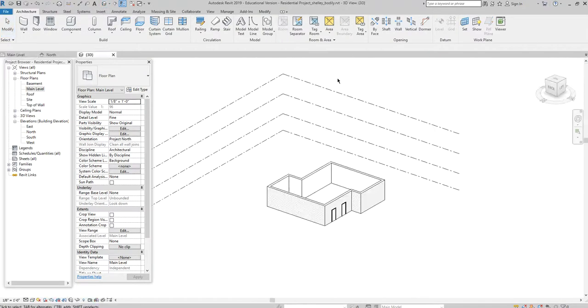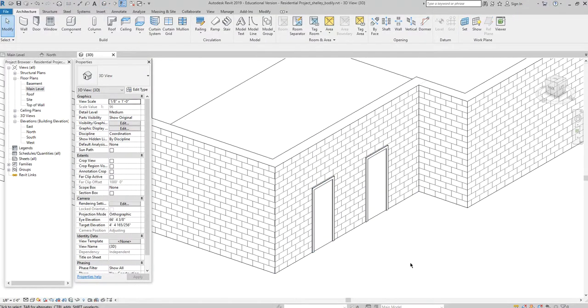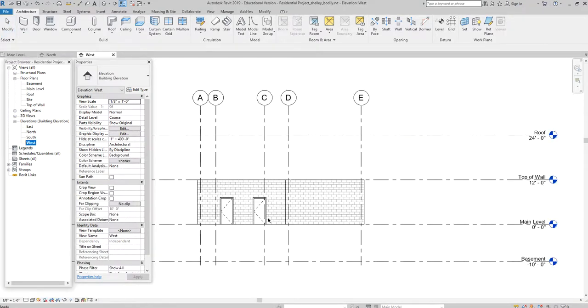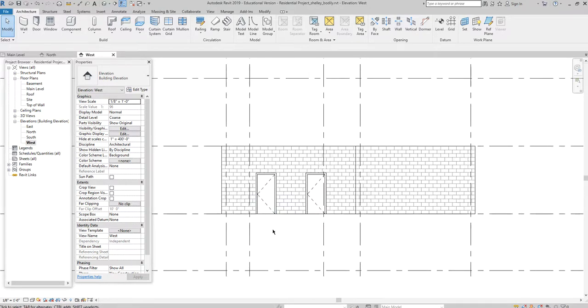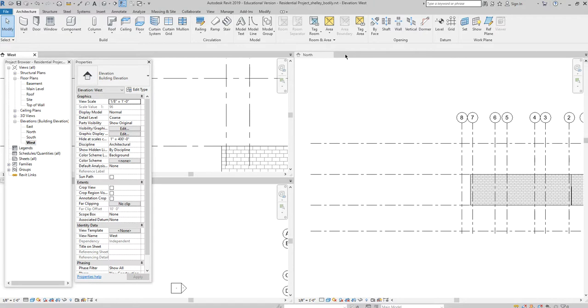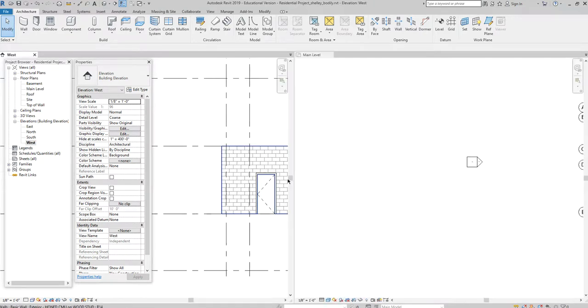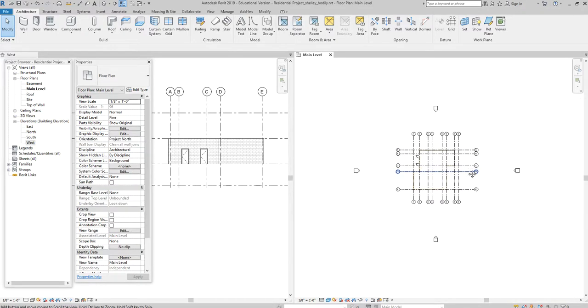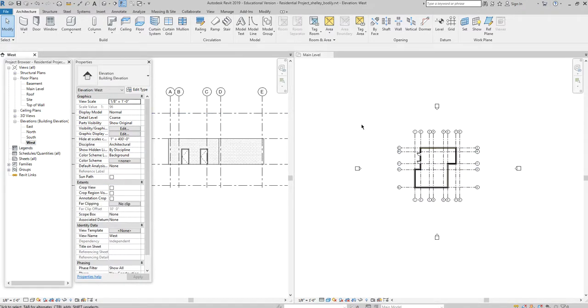And what that looks like in 3D, oh, look at that. When I create the door in 2D, it magically generates the elevation view in 3D, okay? So let's see, what side of the building is that? That's the west side. So we'll look at the west side elevation, and I see my doors appear, okay? Window tile, WT, and I can open up the two views at the same time. Click here, zoom in and out, click here, zoom in and out, right? Just to look and see what's happening.